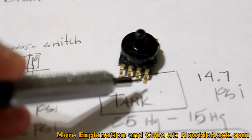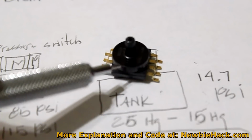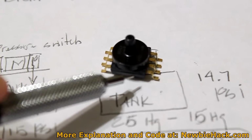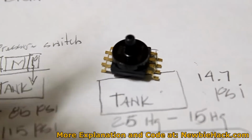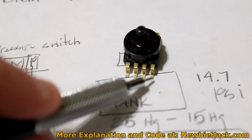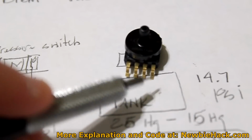This is a Freescale sensor, and it has a silicon substrate inside and a die inside, and the silicon gets pulled up with some leads that are flexed in a way that will change the resistance inside. There is a place for voltage and ground, and there is a voltage output, which would be an analog output, and that would be connected to the ADC of the microcontroller.